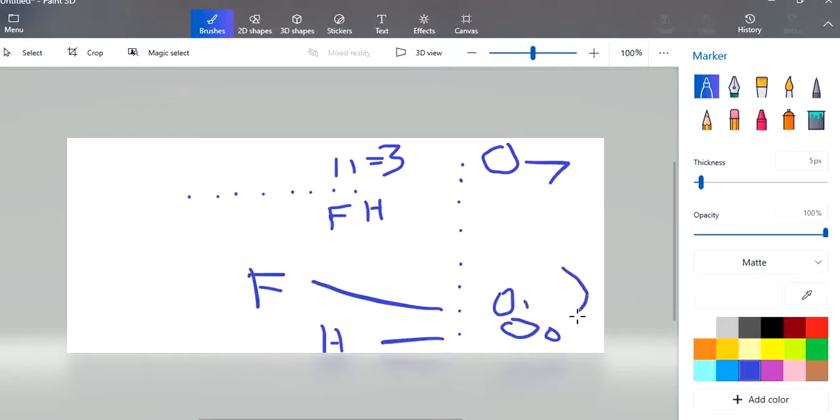We are only using the first two outputs, others we don't care about, we are not using them. We are using only the first two, heater and fan. The heater is on bit number 0, the first output, and the fan is at the second output. Bit 0, bit 1, which are actually output number 1 and output number 2, or O0 and O1. Clear?